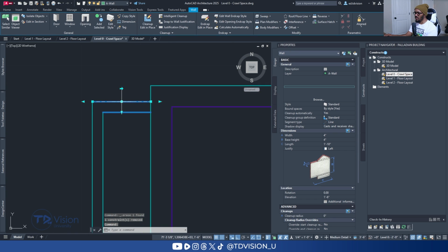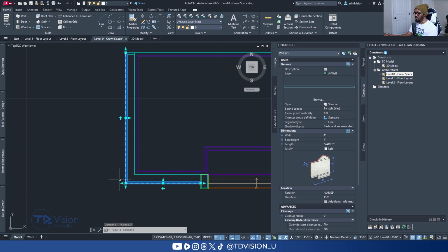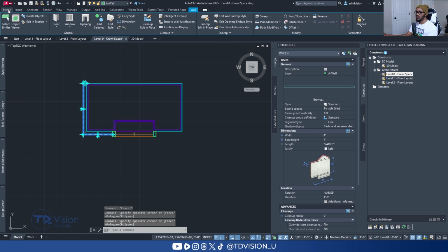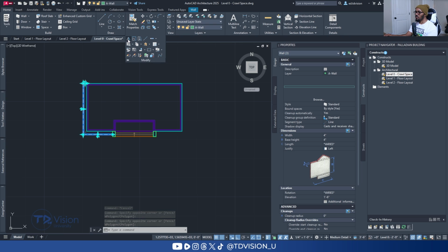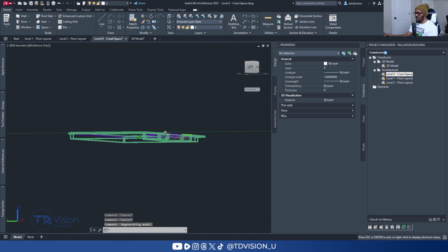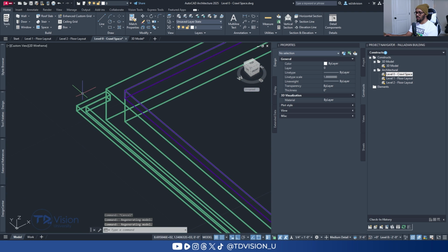And then this wall here, I probably could line it up with the back of the building just like that. And then I'm going to mirror all of this on the other side. So let's go like so, mirror. All right, so that's that. And so we have our little planter wall, except that it is floating in the air. That's not good.